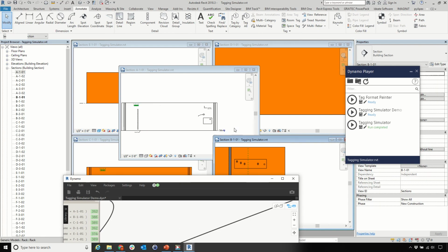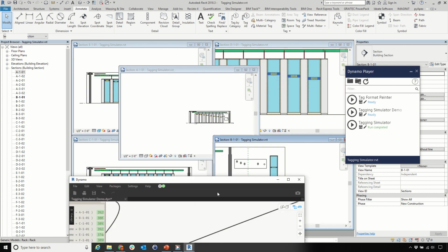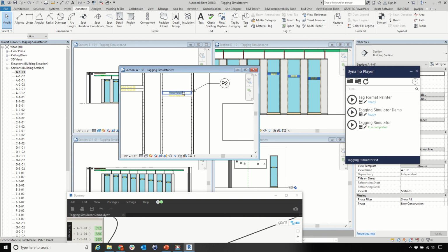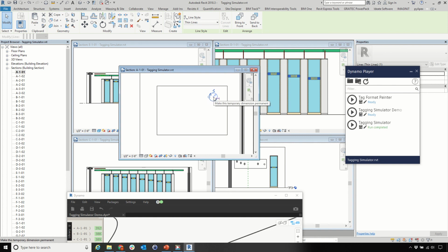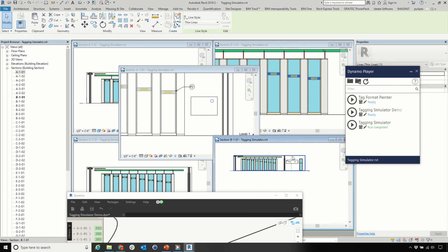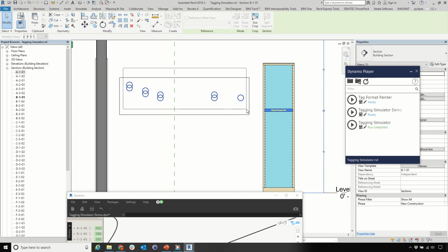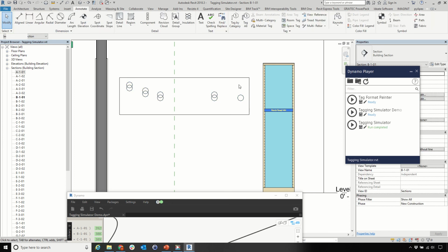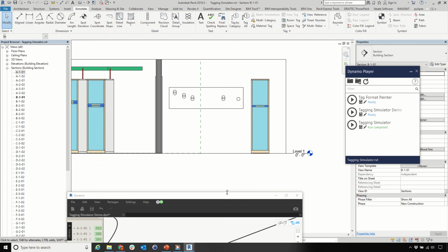And I have this source view. Now it's invisible because I turned this on. On the source view, I know the UV is probably, if that's 0, this is 1. Here is probably 0.8, 0.8. Because I know the source is 0.8, 0.8, I come to this view, take that as the new surface, and examine all the patch panels' locations, and find the closest one to a 0.8, 0.8 dot on this surface. That's how I find this patch panel.